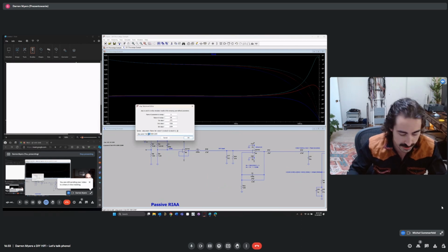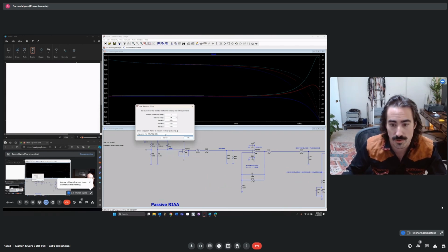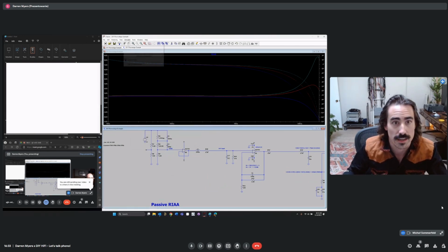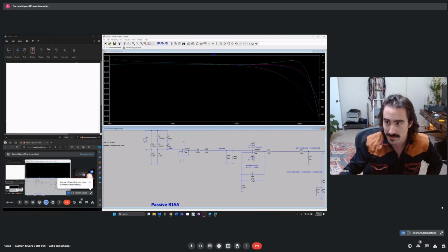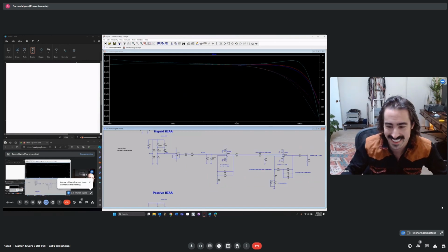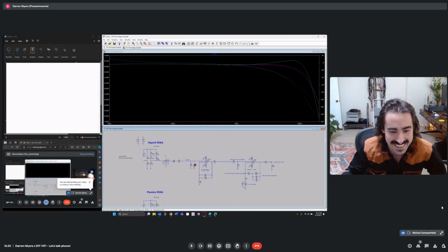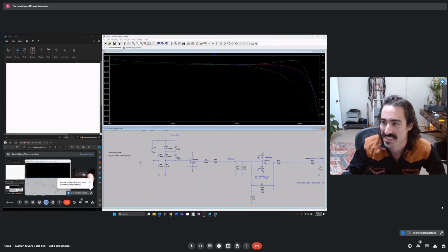Let's start now at 100 pF, go up to 120, and then we'll do one at 220, and let's look at what that brings. Yeah, it's important to use real values which you can get capacitors in, which is usually the E96, E48, and so forth. Yep, exactly.